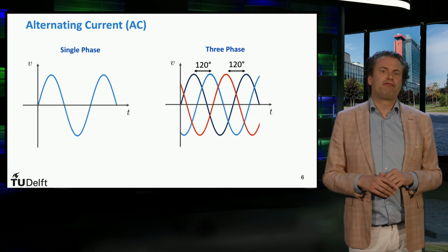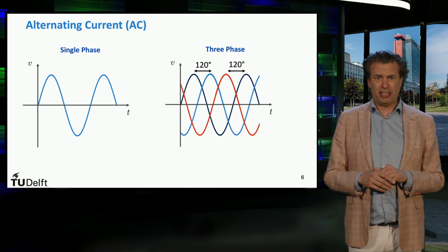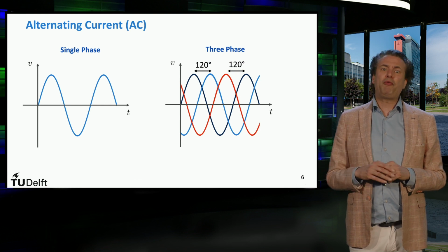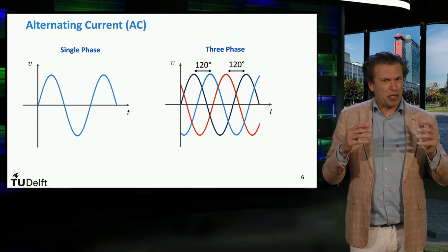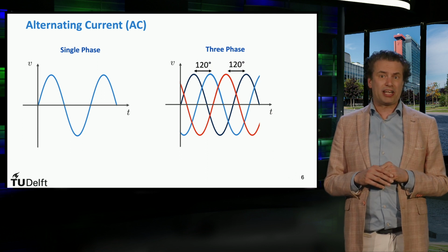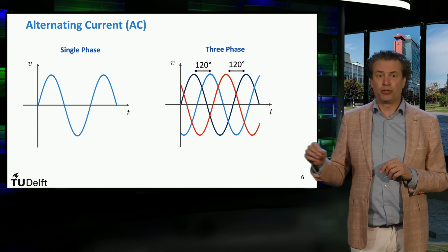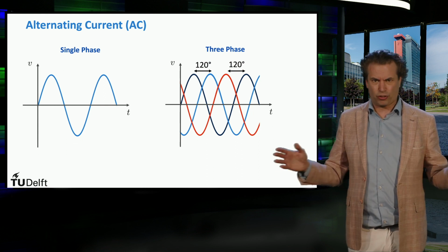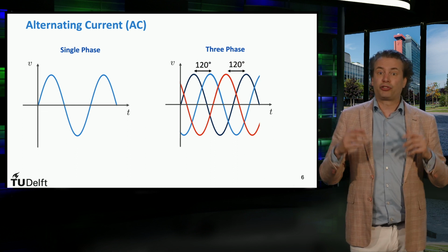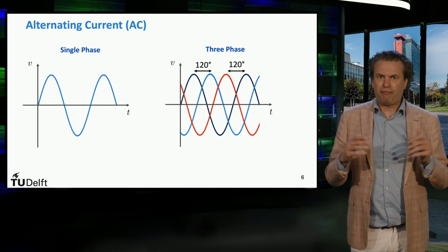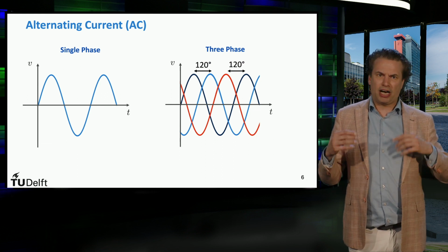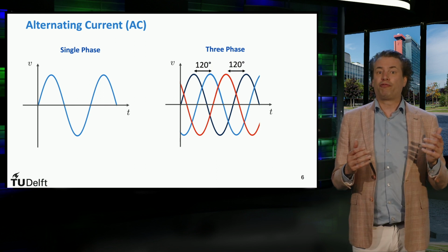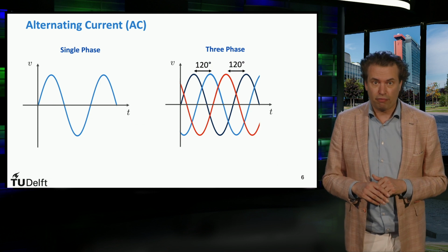In 3-phase power, the voltage on each wire is phase shifted by 120 degrees relative to each of the other wires. A 3-wire, 3-phase circuit is usually more economical than an equivalent 2-wire single-phase circuit at the same line-to-ground voltage because it uses less conductor material to transmit a given amount of electrical power. A 3-phase system includes 3 wires and a neutral wire. 3-phase power is mainly used directly to power large induction motors, other electric motors and other heavy loads. Small loads often use only a 2-wire single-phase system.